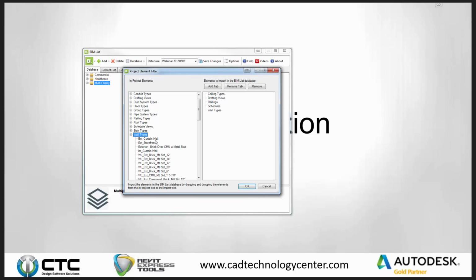So I'm going to expand out my wall types. I'm going to find wall types that I actually want my end users gaining access to. Some of these I may not want to show. They might be poorly formed wall types, or maybe they're wall types that I just don't want. Or maybe I want to break these apart into two separate groups here. Maybe I want this to be wall types exterior, and I want to have wall types interior.